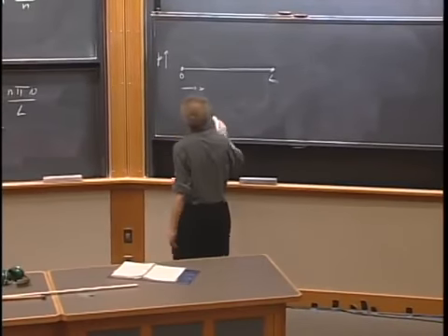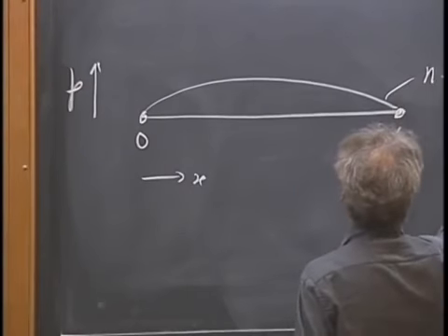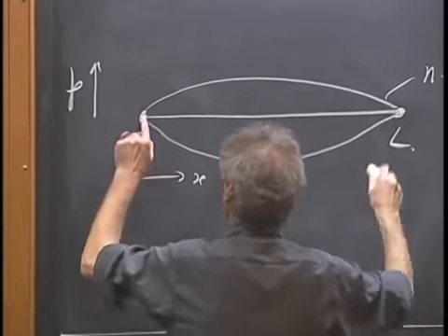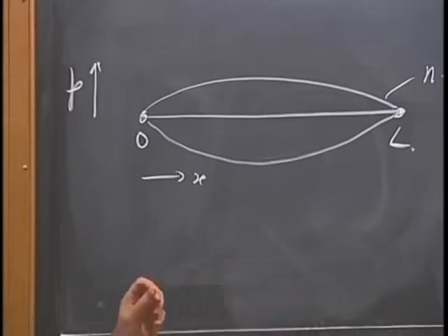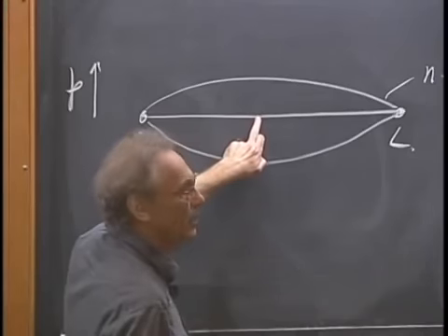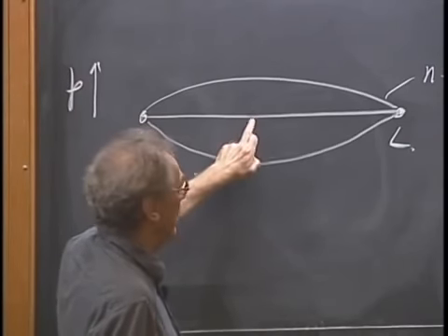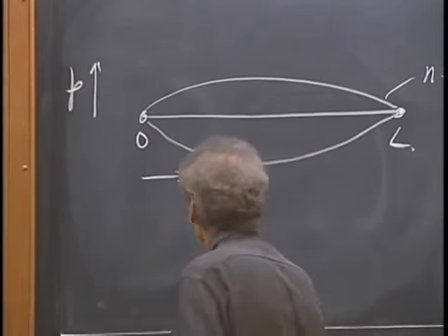For n equals 1, you would get this mode. There must be a pressure node here and there, because we can never build up pressure. It's connected with the universe. You can never build up overpressure. And so the pressure builds up here positive, and then later in time it will be negative, and then positive, and then negative.